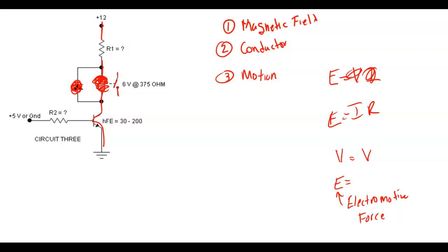Now I'm putting this diode in here reverse biased. So when the coil discharges, it's going to discharge through the diode. So here I'm going to charge it up again, discharge it, charge it up again, discharge it, charge it up again, discharge it. What don't you see anymore? So that's the purpose of the diode. It makes the coil discharge. You charge it up with the magnetic field coming out, and when it discharges, the magnetic field comes in. So the EMF that it creates is in the opposite direction of the applied voltage.